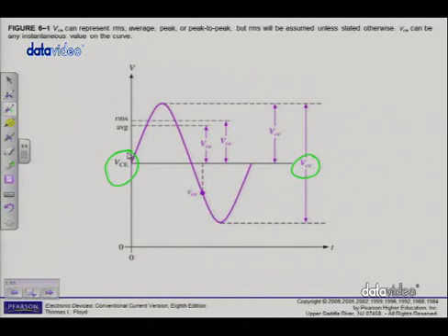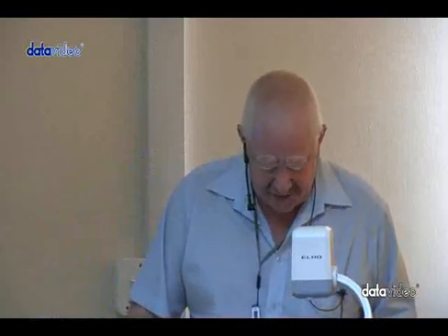Alright, so familiarize yourself again here, what are RMS, average values and so forth, which will also be used in the semester. If you refer back to the textbook, you can mark there in the textbook, the first sentence there says DC quantities were identified by non-italic uppercase subscripts such as IC, IE, as you can see there. Lowercase italic subscripts are used to indicate AC quantities of RMS, peak and so forth, as indicated there. Instantaneous quantities are represented by both lowercase letters and subscripts, as you can see there, small i and small c and so forth. Just below the figure, we can also see, for example, Rc with a lowercase c is referring to the AC resistance at the collector, and RC with a capital C, of course, refers to the DC quantities.